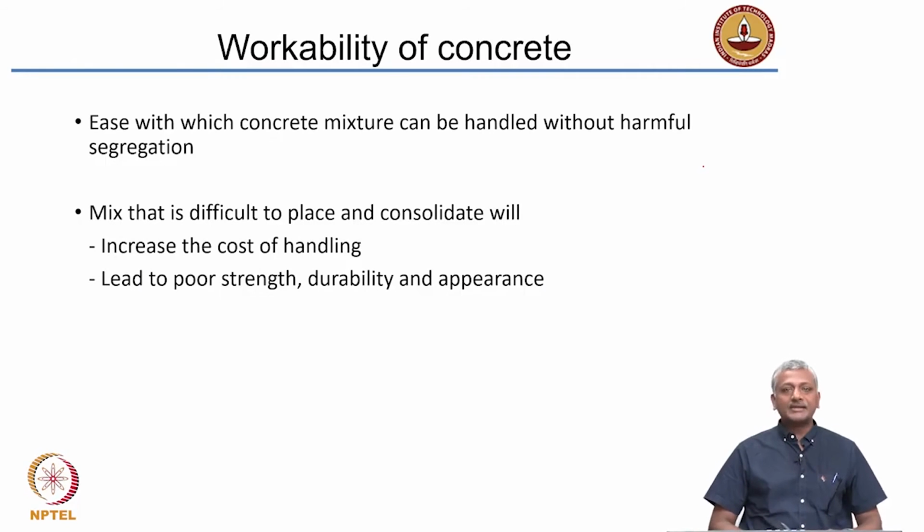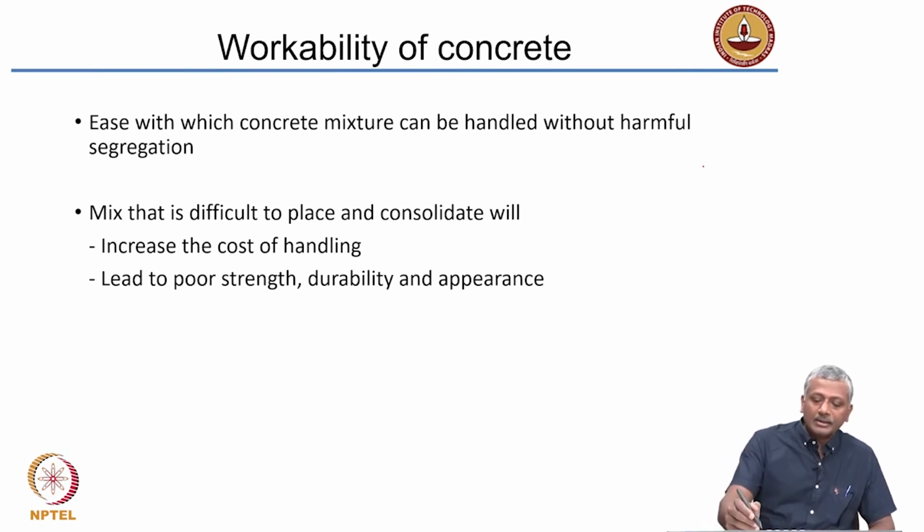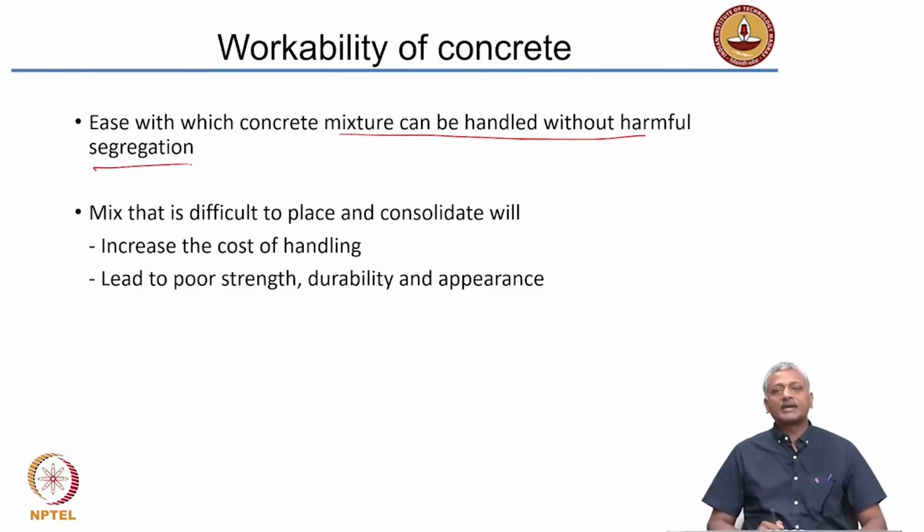So, workability, as I said, is the ease with which you can handle the concrete and place it, compact it and so on. So, generally what you say is, the ease with which concrete can be handled without harmful segregation. What is segregation? It is a separation of the constituents of concrete.